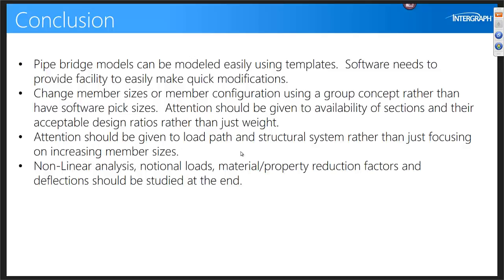How do you consider wind load due to pipes? Would that be possible in GT Strudl? Wind load on pipes, usually people would use Caesar to design their piping. The company that I used to work for used Caesar to generate the piping loads, and they also gave us the piping wind loads.